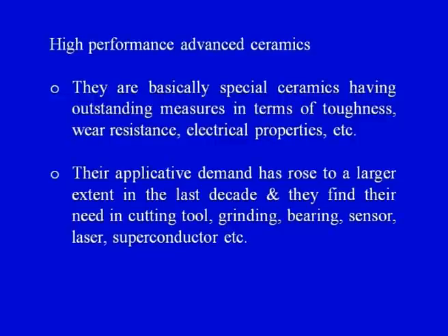High performance advanced ceramics is the next category on the basis of application. They are usually special ceramics having outstanding measures in terms of toughness, wear resistance and electrical properties. Their applicative demand has risen to a large extent in the last decade, and they find their need in cutting tools, like the carbide tools we sometimes use for machining. We can have different types of hard tools used for machining, grinding, and ball bearing applications are also among the latest applications of ceramics.